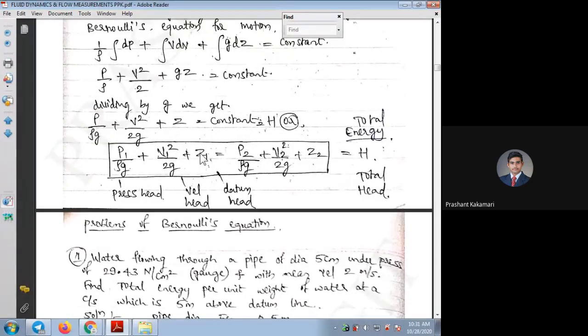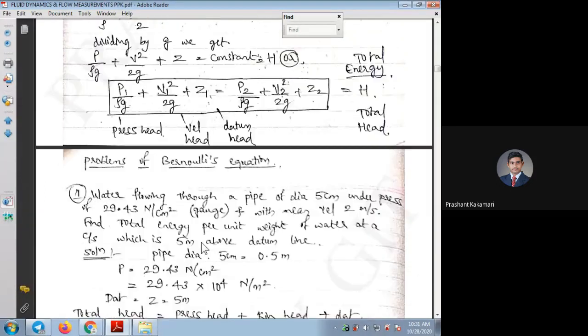Datum is mentioned, 10 meters and 6 meters, but velocity is nowhere mentioned. To relate the velocity, what they have mentioned is the discharge. Are you understanding? So to find the unknown pressure, even though both velocities are not given, you can go by discharge or the continuity equation.